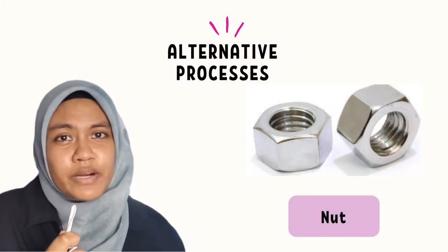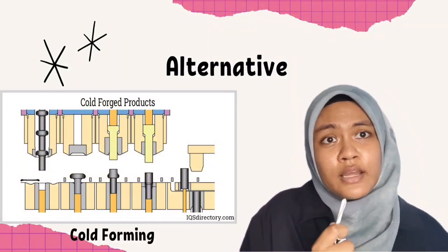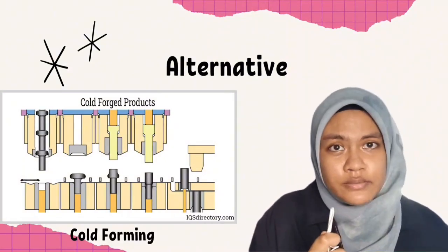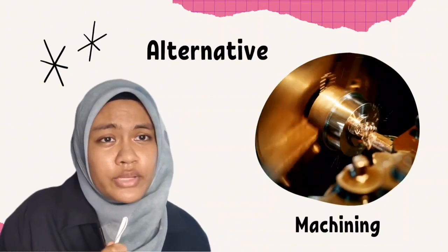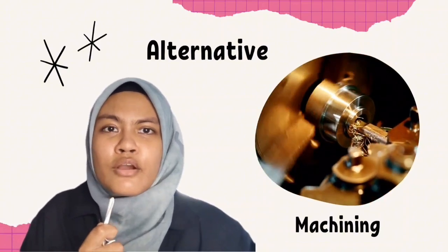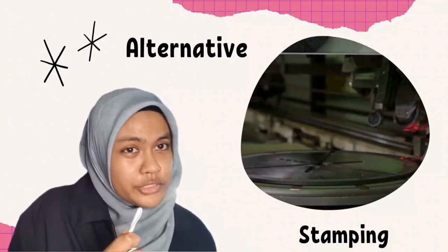And then the last part is the nut. You can use cold forming. This method can affordably produce big numbers of nuts. The second alternative is machining for extremely precise or unique nuts. And then tapping: for a less important application, tapping the internal threads afterward can be an option.